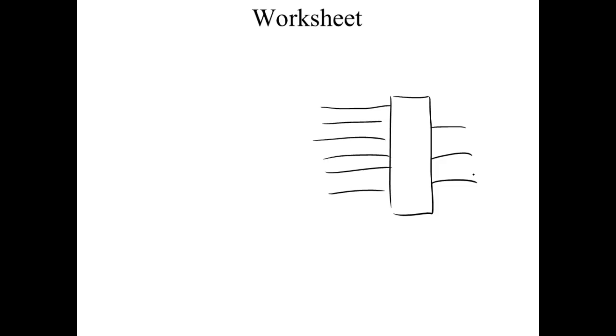And we kind of saw that on our trainer, right? You understand, when we came over here and we had four inverters, and then we said, okay, we wanted to draw a truth table of the circuit. Well, that thing had 4 inputs and 4 outputs. And then you filled in the chart, right? So that was a circuit, not very complicated. Well, the way we calculate the number of possible input combinations is we count the number of inputs, 1, 2, 3, 4, 5, 6, and I'd say 2 raised to the 6th power, and this would give us the number of possible combinations we could put on those inputs, which would be what?